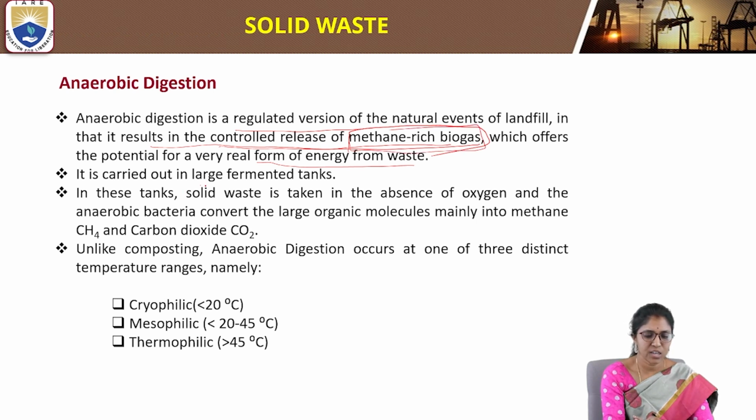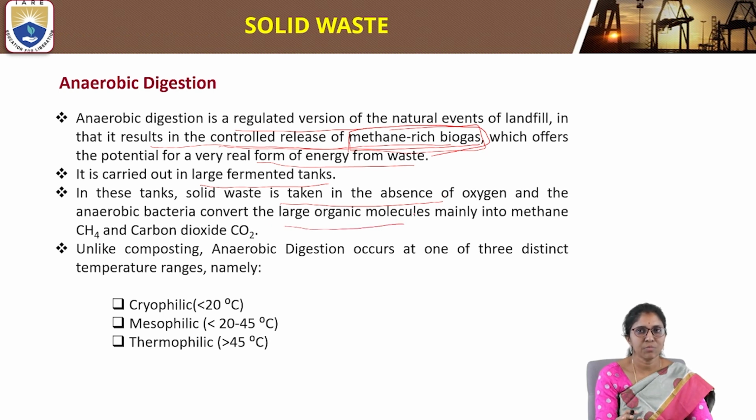Anaerobic digestion is carried out in large fermentation tanks. In these tanks, solid waste is taken in the absence of oxygen, and the anaerobic bacteria convert large organic molecules mainly into methane and carbon dioxide.